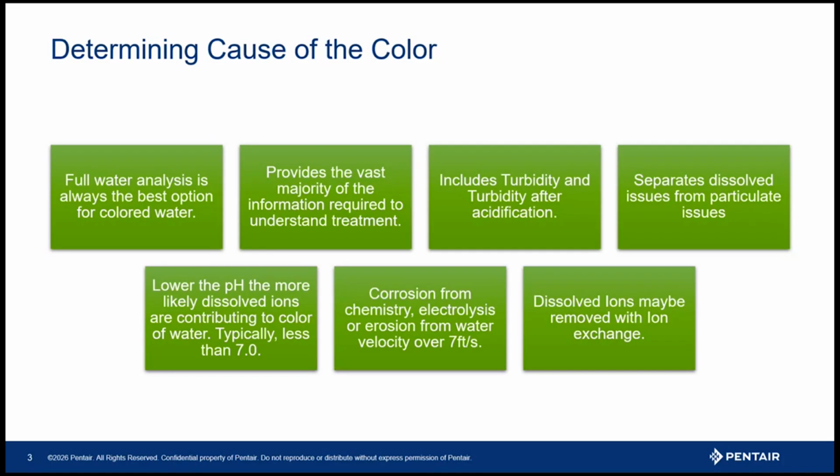And this is a visual representation of what turbidity looks like visually at different units. It's interesting to note that the federal standard is less than 5 NTUs for water. And in our commercial side of the business, anything over 0.3 NTUs, we like to specify pre-filtration in commercial applications.